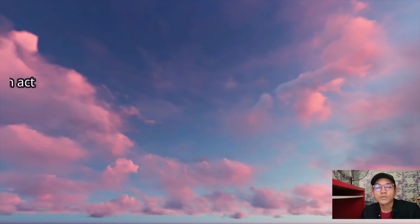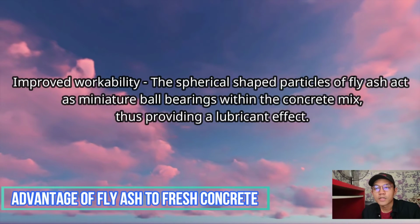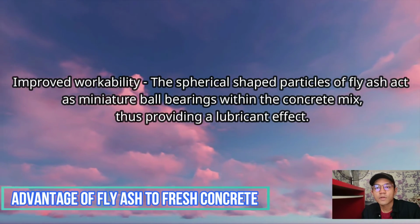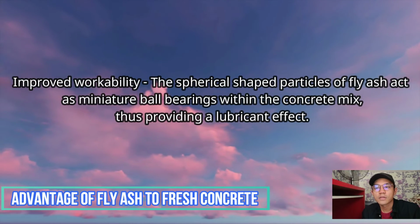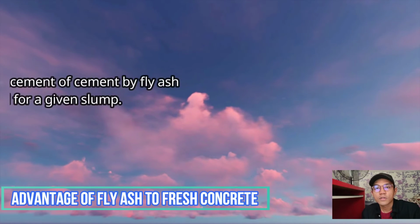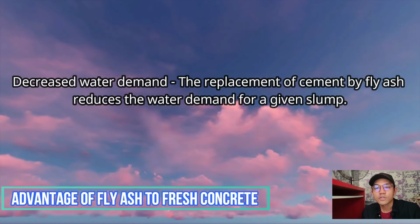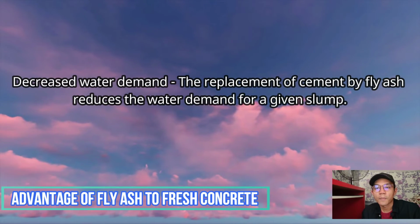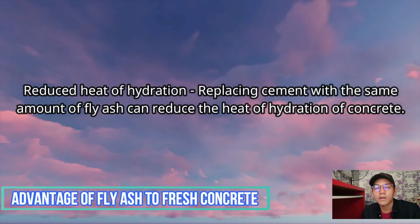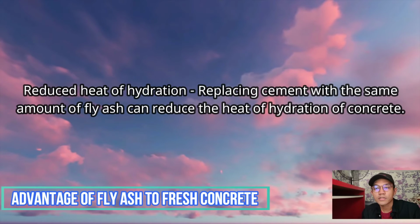Advantages of fly ash to fresh concrete. First, improved workability. The spherical shaped particles of fly ash act as miniature ball bearings within the concrete mix, thus providing a lubricant effect. Second, decreased water demand. The replacement of cement by fly ash reduces the water demand for a given slump. Third, reduced heat of hydration. Replacing cement with the same amount of fly ash can reduce the heat of hydration of concrete.